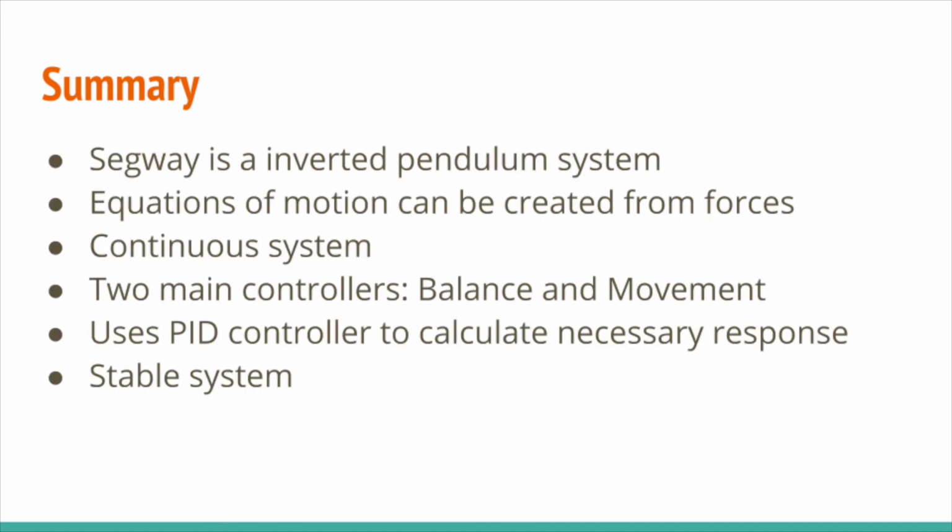In conclusion, the Segway is made possible by dynamics and control through linearized equations of motion. The system is a continuous one that has two controllers, balance and movement. The controllers use a PID subcontroller within them, and the result is a stable system.